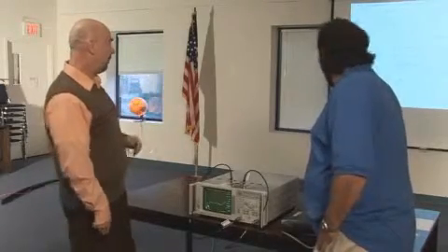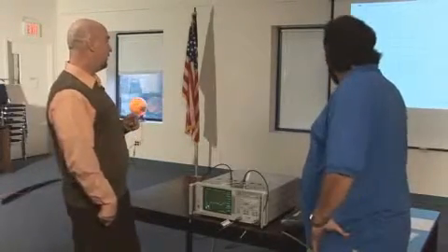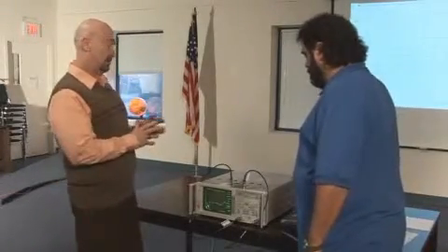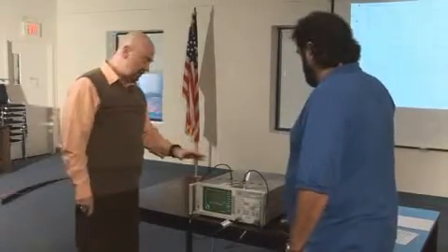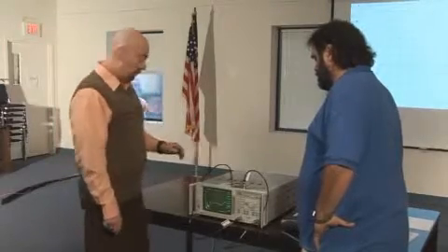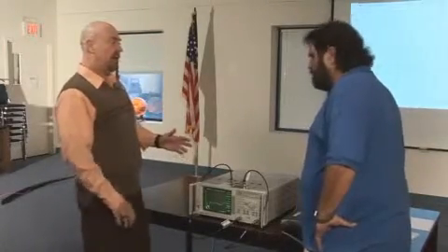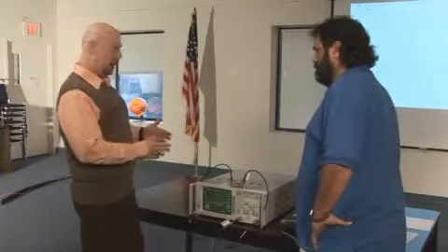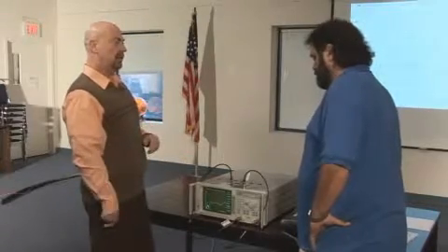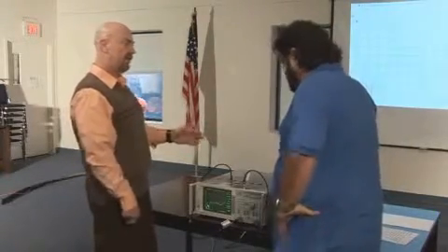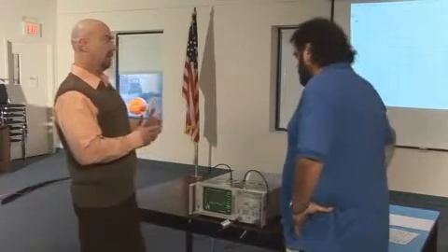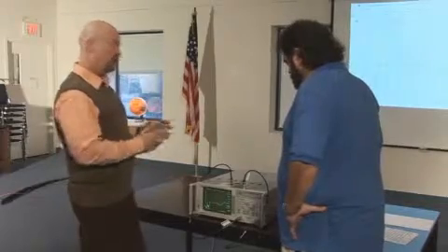Great. Right now I've got this set to sweep from about 300 kilohertz up to about 800 megahertz. And we're going to look at some typical situations that we fall into. When you have one of these devices, the first thing you need to do is get your test setup out of the way. So what we have here is a test setup with 2 cables, and we don't want this device measuring any of the characteristics of our test fixture. So these devices incorporate a feature which allows you to put a straight through in, and it will null out and save any characteristics of these cables. That way what you're reading is indeed what you want to read and no additional factors.